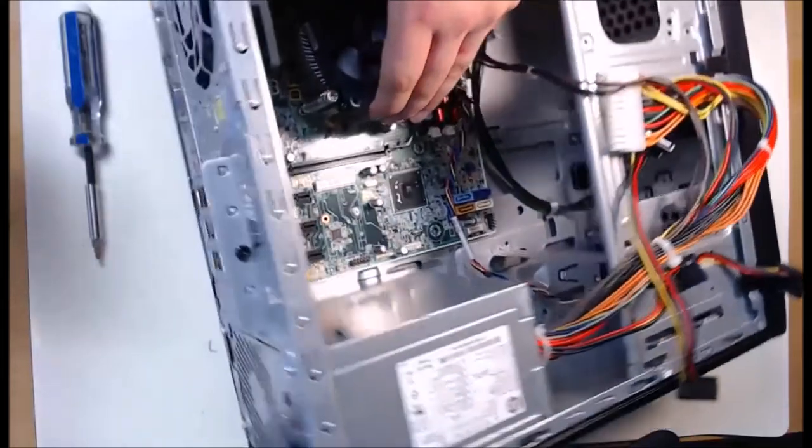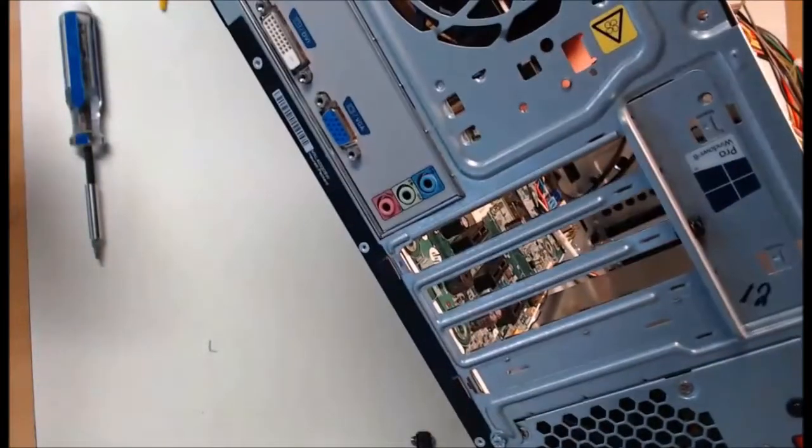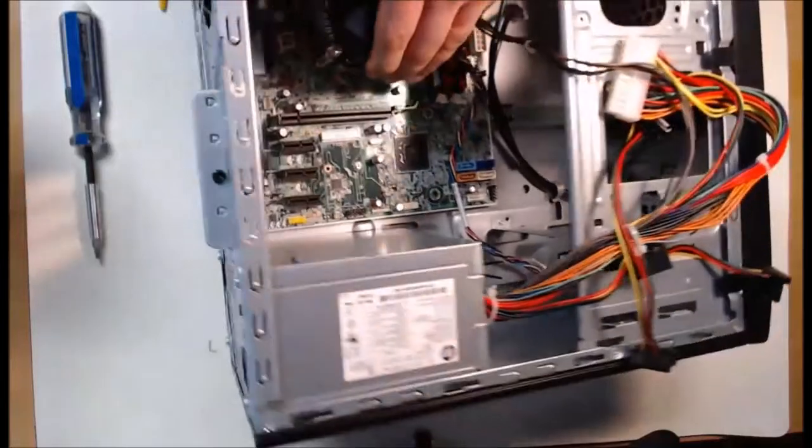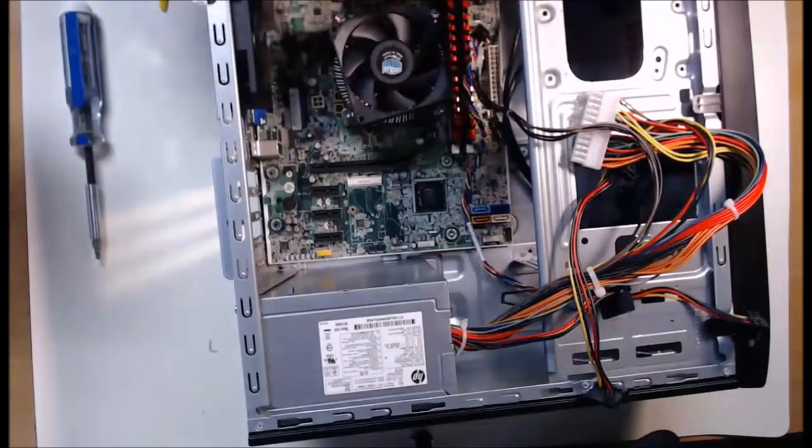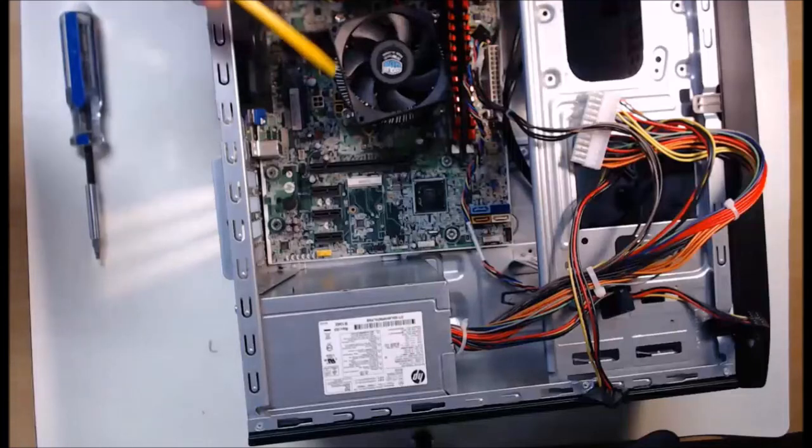At this time, we can use our screwdriver for step 6, installing the screws into the motherboard standoff. One by one, we will install the motherboard screws. Make sure not to install the screws too tight, as you don't want to crack the motherboard through excessive force. Don't worry about the screws not being overly tight, as we have a good amount of screws to keep this motherboard in place.